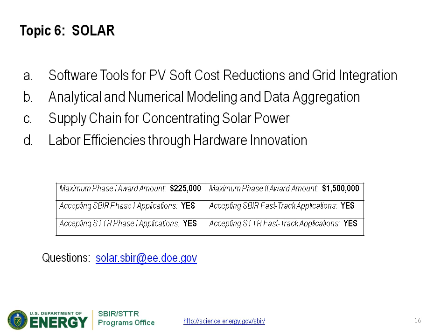The first being molten salt, flexible and rotating couplings, suitable for molten salt, operating at about 550 C, suitable for a 30-year lifetime. Also CSP mirror cleansing systems that can improve annual average trough and heliostat mirror reflectivity while reducing cost and water consumption. Some of the metrics associated with these 2 solicitation subtopics, again, are identified in the solicitation.